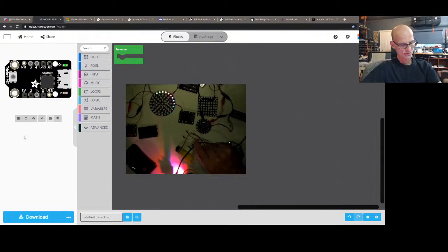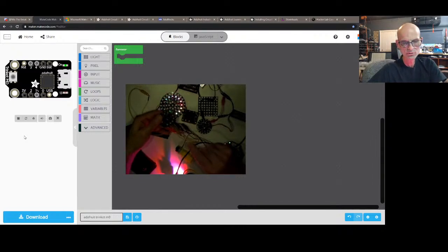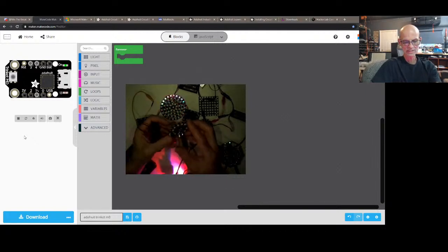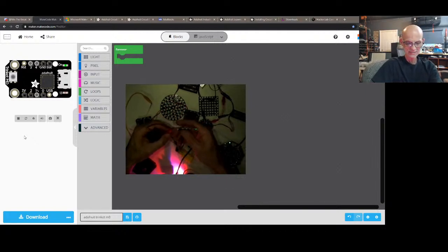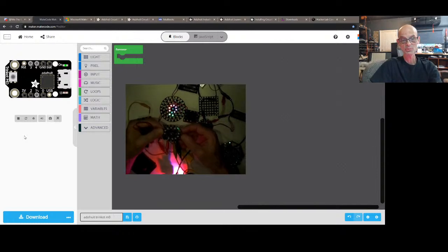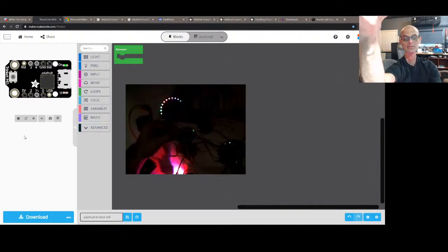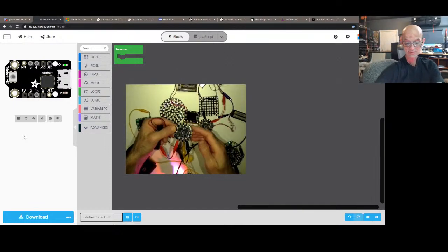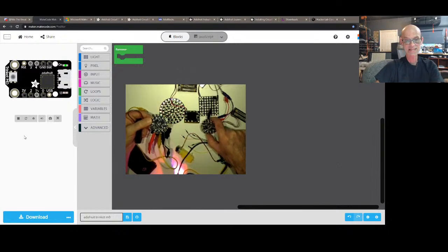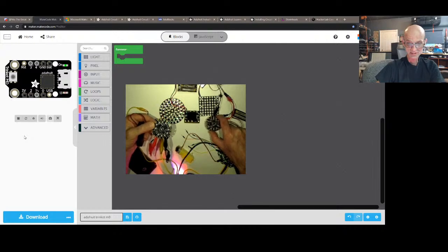And then they moved on to the Circuit Playground Bluefruit, which is the nRF52840. This is a Bluetooth LE device, same form factor as the Circuit Playground Express. Let's see, did I get that wrong? Yeah, there we go. But it has a Bluetooth radio. And so you can communicate between devices with this particular version. The Circuit Playground Express has an infrared blaster and receiver on it, so they can communicate with other devices as well with the infrared blaster.